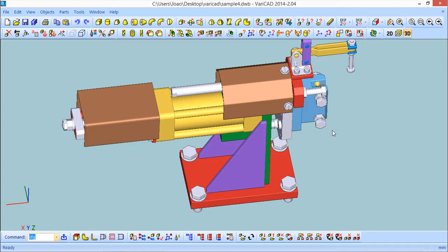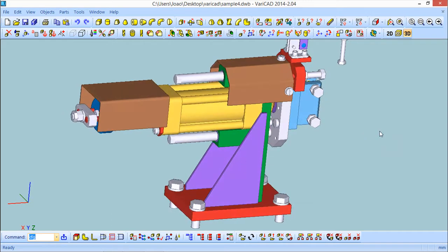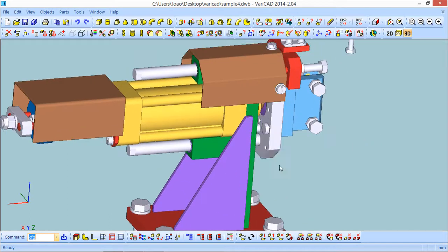On the anti-aliasing you should put, instead of application controlled, which is the typical setting of the graphic adapter for these applications, something like override any application setting. So your graphic adapter should control the application. And this is important because the anti-aliasing will help you to have a better display of the 3D, and this is something that I will try to show you.